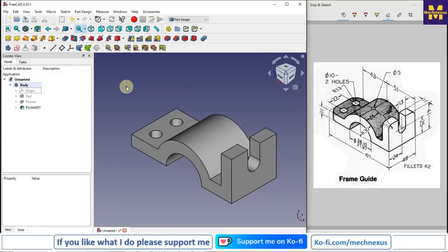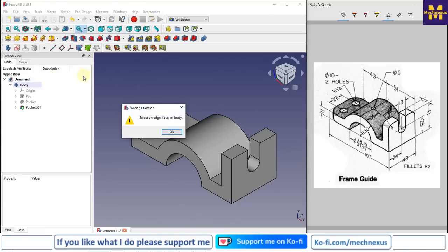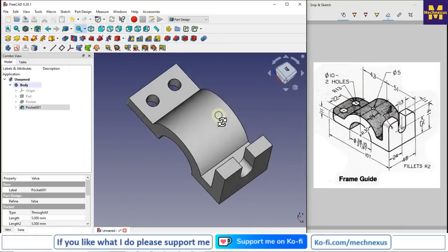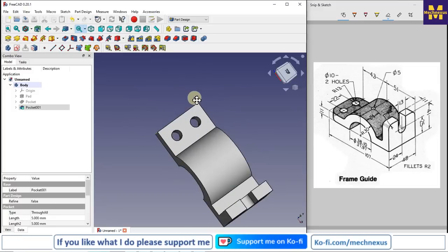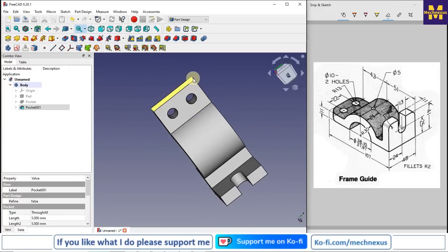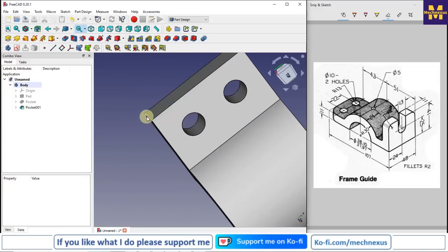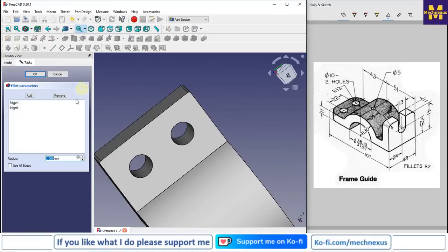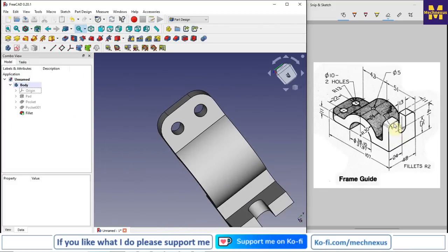Okay, now we will go to the fillet tool. Sorry, first we will select our edges. So this edge and this edge and this edge, and say fillet. So fillet is here R13, so I will give 13 here and I will say OK.